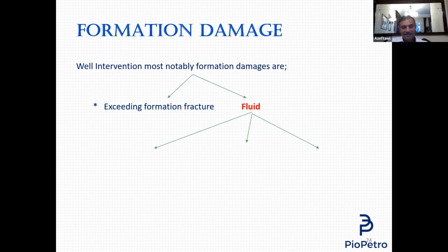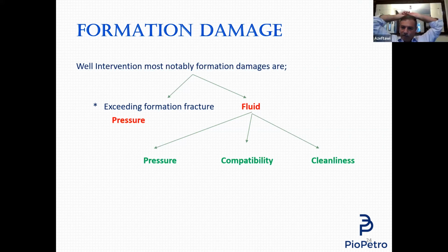The other thing is fluid. How will fluid damage formation? We have three things. Number one, it is pressure. If you put fluid that creates a hydrostatic head much greater than formation pressure, you damage it.